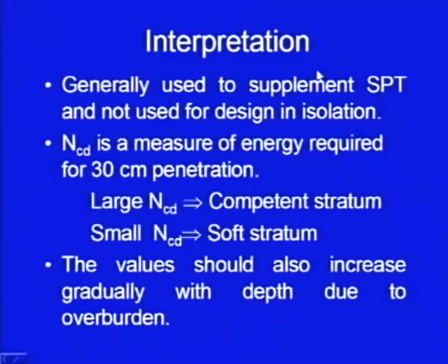What I mean is that if you have some DCPT values, we should have some confirmation from other tests also. For example, if you have SPT and DCPT data together, then you can have a correlation between them, and then using the DCPT data you can go for the design. So, generally it is used to supplement the SPT and not directly used for design purpose.